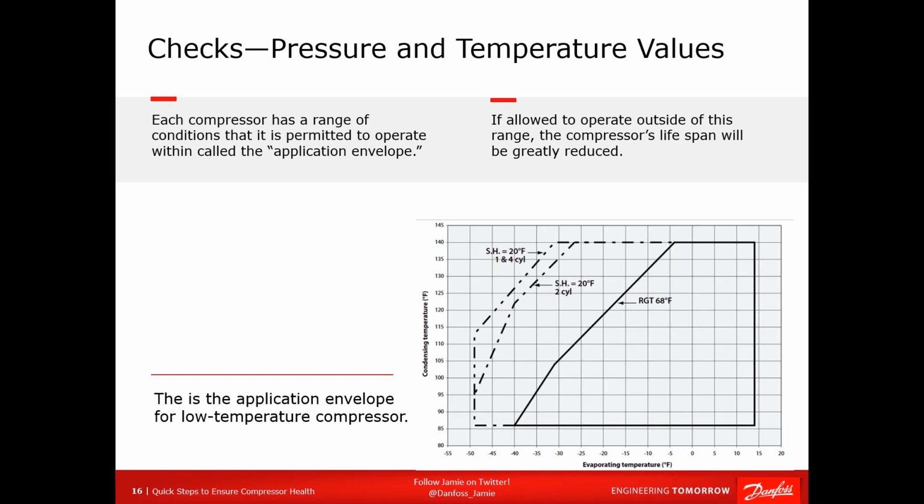Now, when does this happen? I don't know. If the refrigerant's minus 30 and you're going through an unconditioned space at 90, that's a 120-degree temperature difference. So if you have any breaks in the insulation or don't properly insulate, you can very easily pick up 30, 40, 50 degrees of superheat. If you do that and you run this compressor at one of those intersections, it is going to fail relatively quickly.